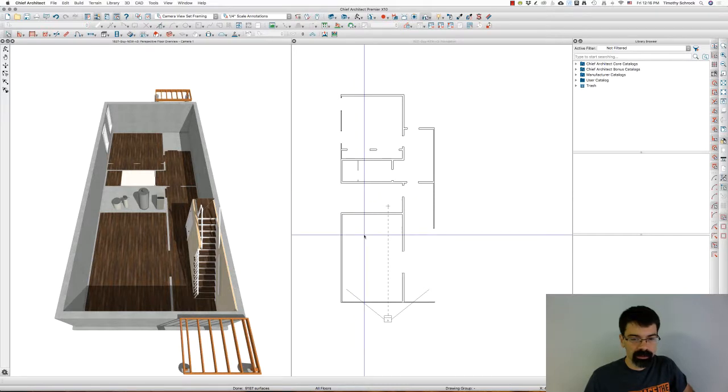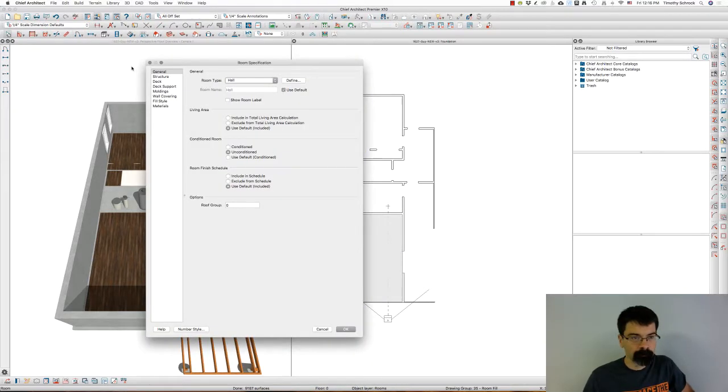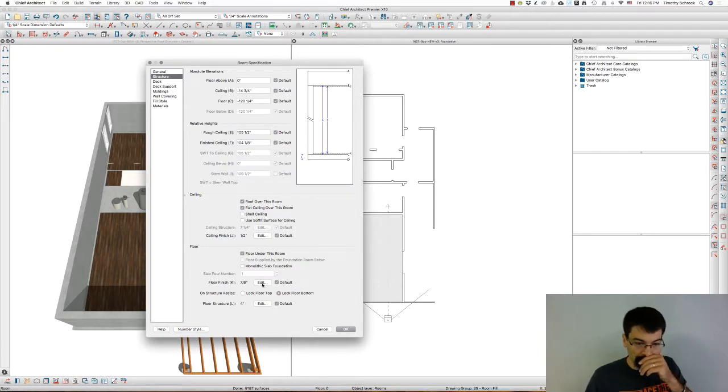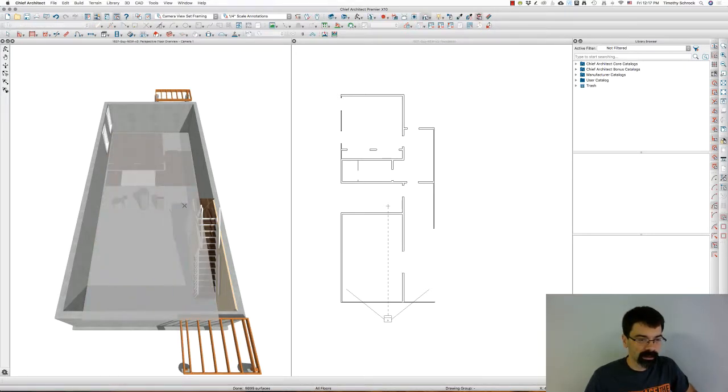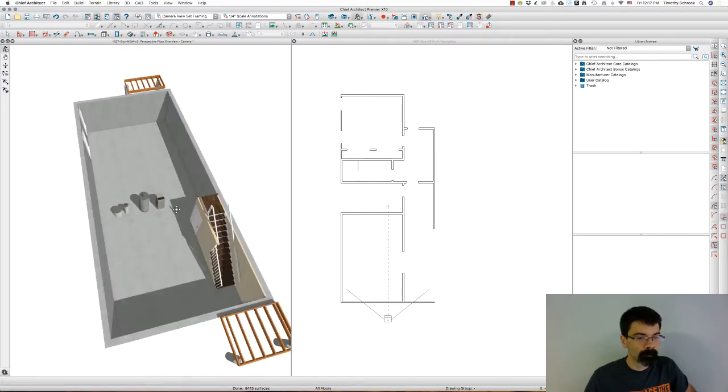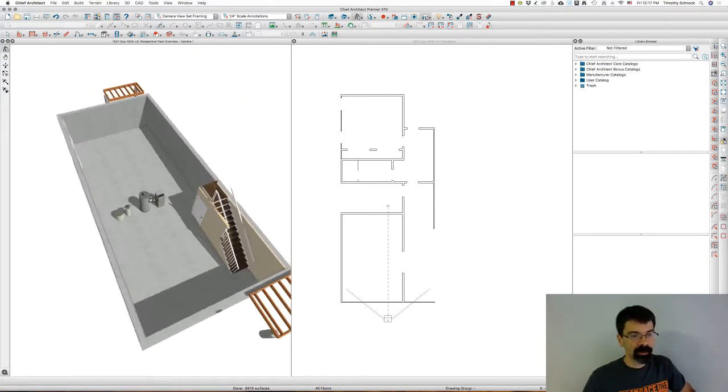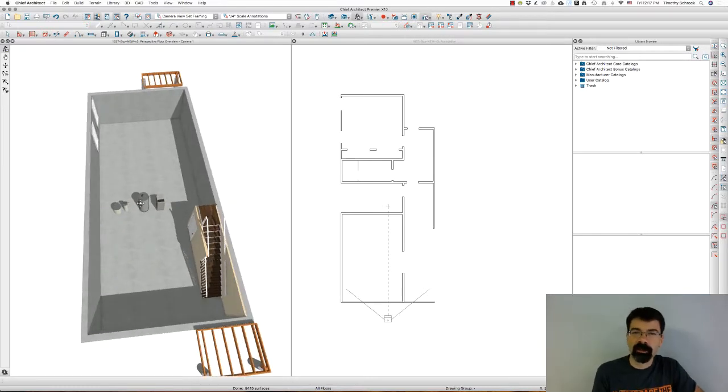And then lastly, all I need to do is change my floor finishes. If I don't want to see them, I could go about it a couple different ways. I could go into the camera view and just delete these surfaces. So when I take a rendering, there we go. Now I take a rendering, and that's what will be built, an unfinished basement. I hope this has been helpful for you, going through the layer controls and the wall types controls so that framing does not get built.